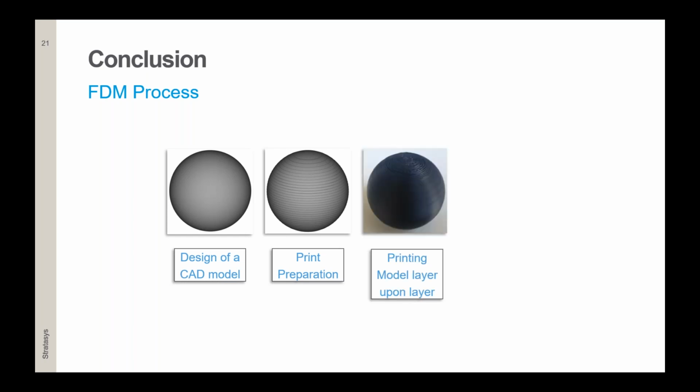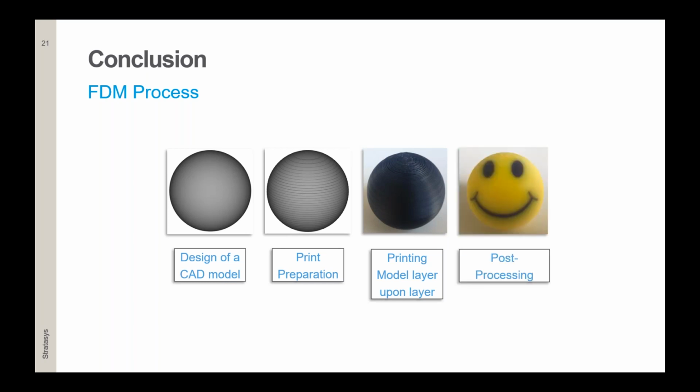There are some advantages and limitations for FDM technology. The layering process might provide stair stepping at certain angles. You need to be careful with thin walls and always look for self-supporting angles to improve this. Even how the parts will be finished might affect your design in a certain way, as you saw from the few examples before.